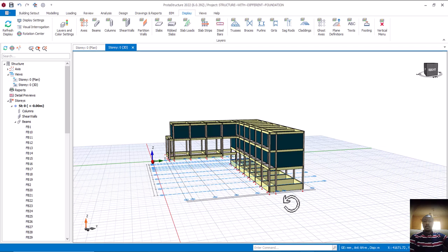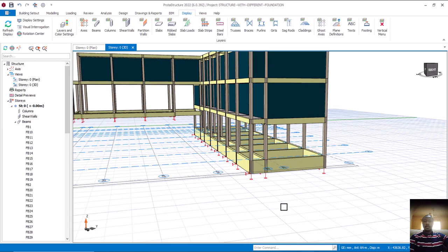Though we have some people who are designing strip footing, but yet they increase their beam depth to 1000, 1001 or whatever, just to make sure that it passes the design. But yes, they are designing strip footing. But based on principle, the maximum beam depth for strip footing is 950. The moment your beam goes beyond that, automatically you are expected to use a beam raft.